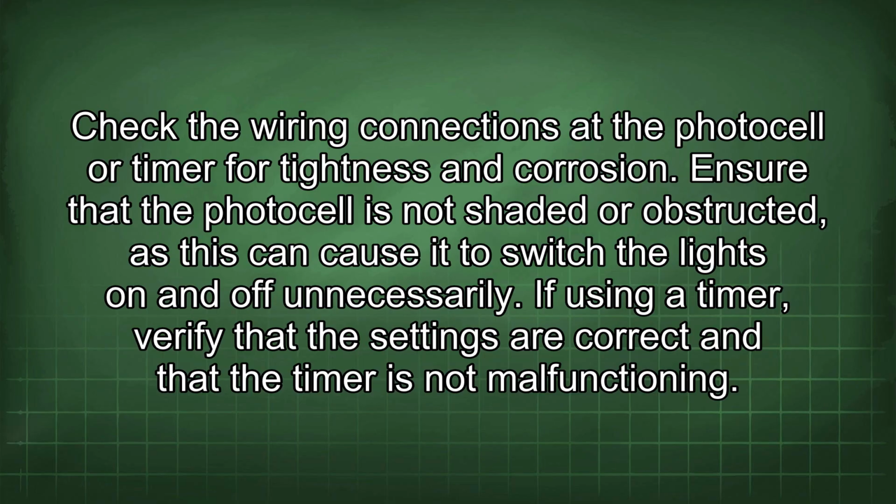Ensure that the photocell is not shaded or obstructed, as this can cause it to switch the lights on and off unnecessarily. If using a timer, verify that the settings are correct and that the timer is not malfunctioning.